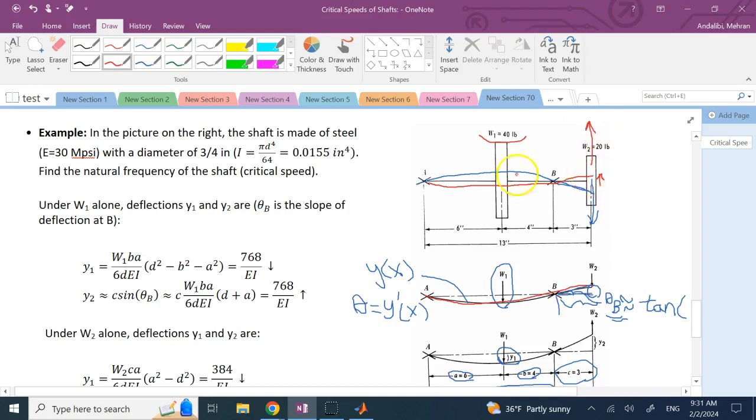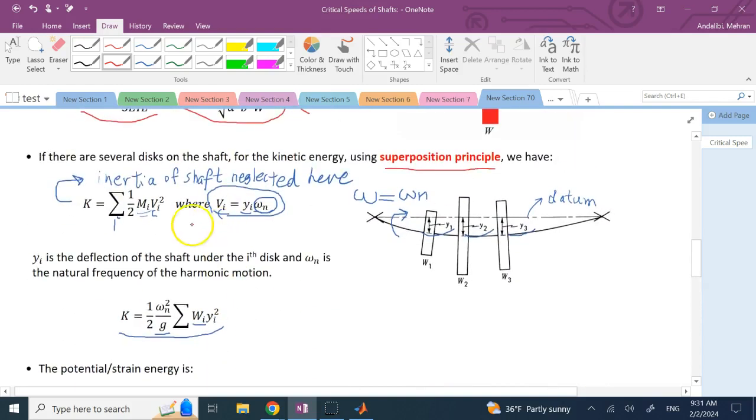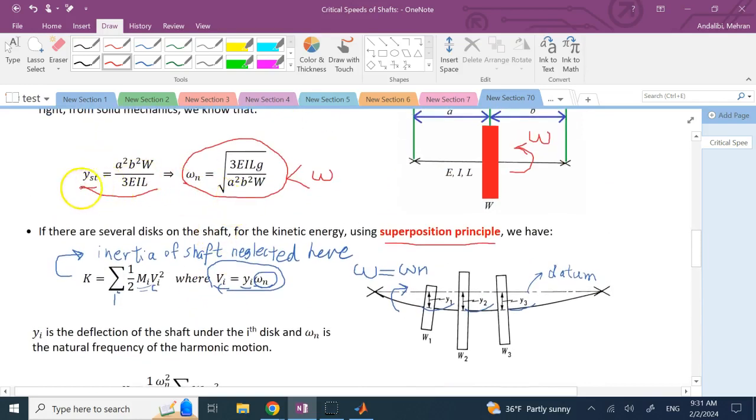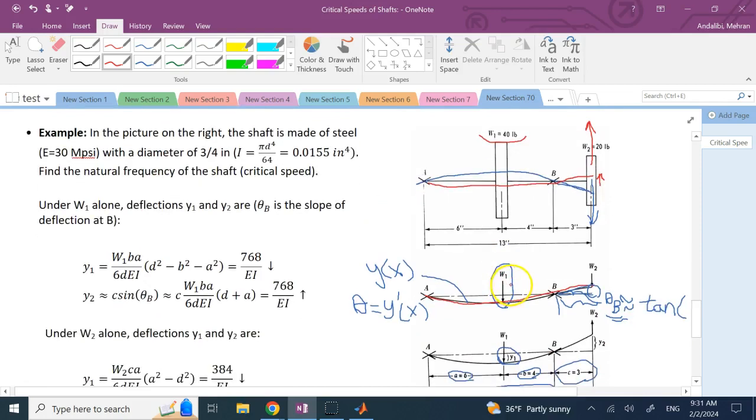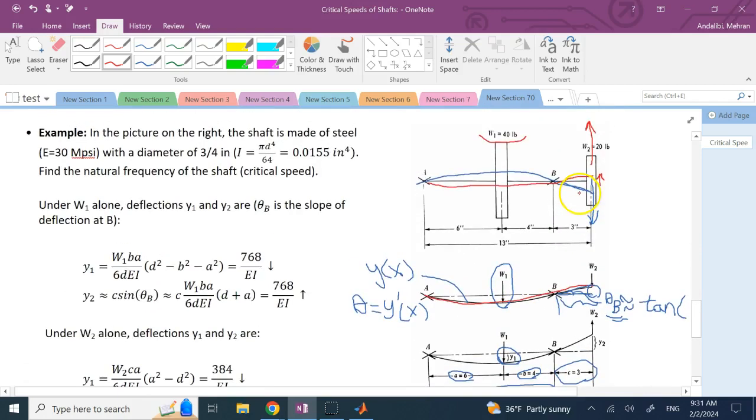So if you want to approximate these dynamic y's that we have over here with their counterpart static ones, you better look at what they do in dynamic scenarios. And for that reason, since the centrifugal force is upward, instead of finding y1 and y2 under a W2 that is downward, you better do it under a W2 that is what?